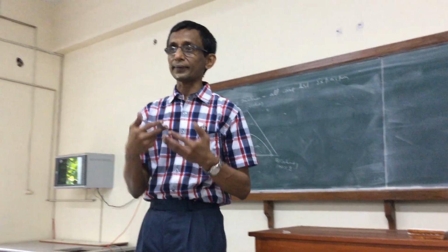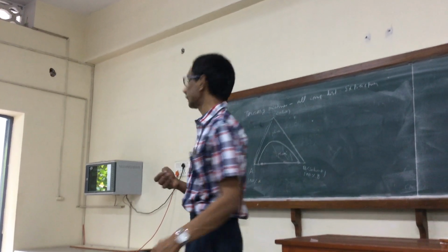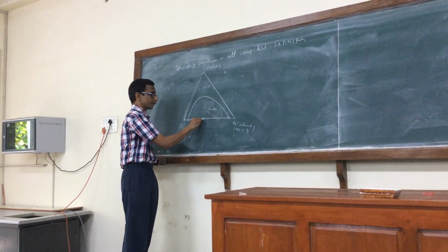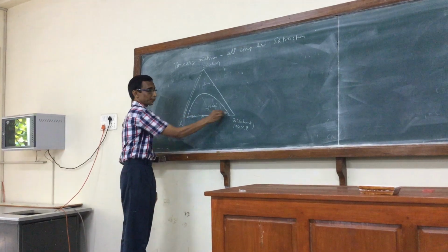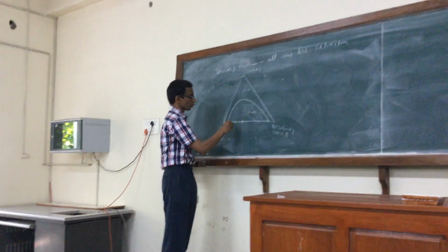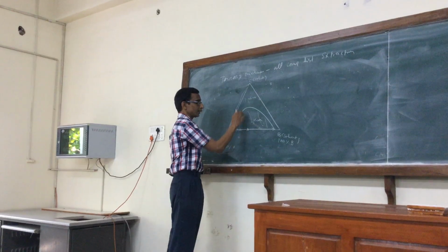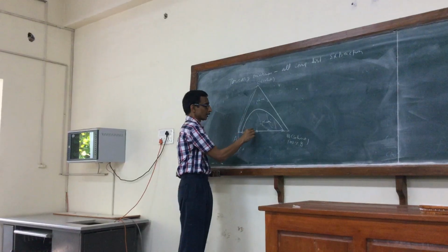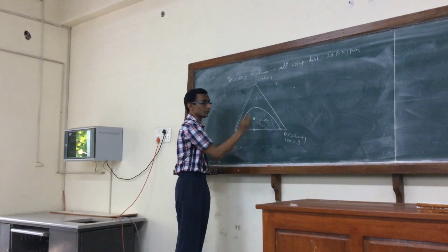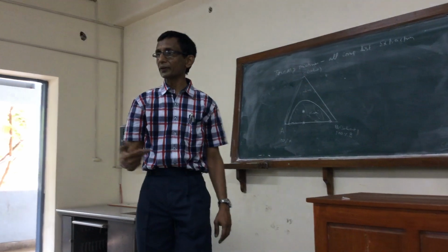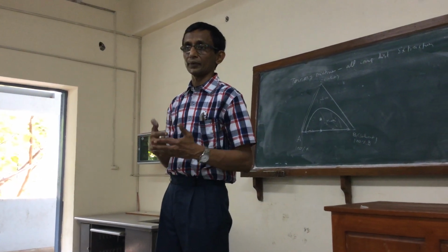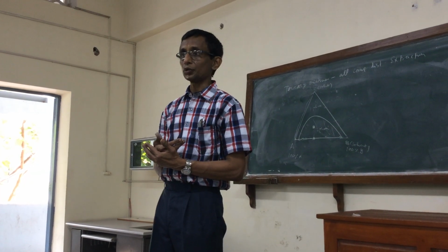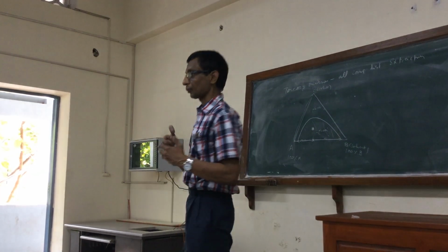So now what happens when you add C to a mixture of A and B, right? So let's say the overall composition. So now I start adding some C. So let's say I have reached this point. Now this is going to separate. And so now when I add C, it's now going to move because C represents the vertical direction here. Right? So we'll get to a point here, let's say. Now I have to specify how this mixture, which has A, B and C, is only the overall composition, how is it going to separate into two parts? So that is what is given by the so-called tie line.